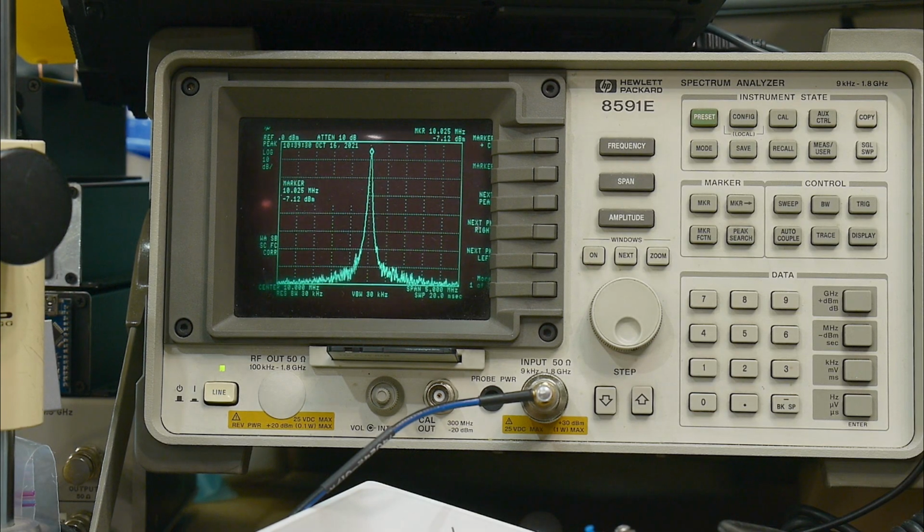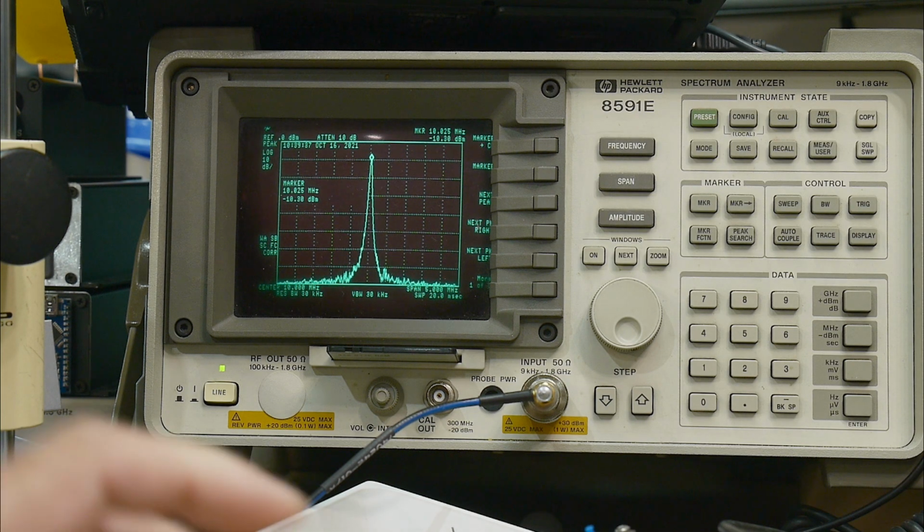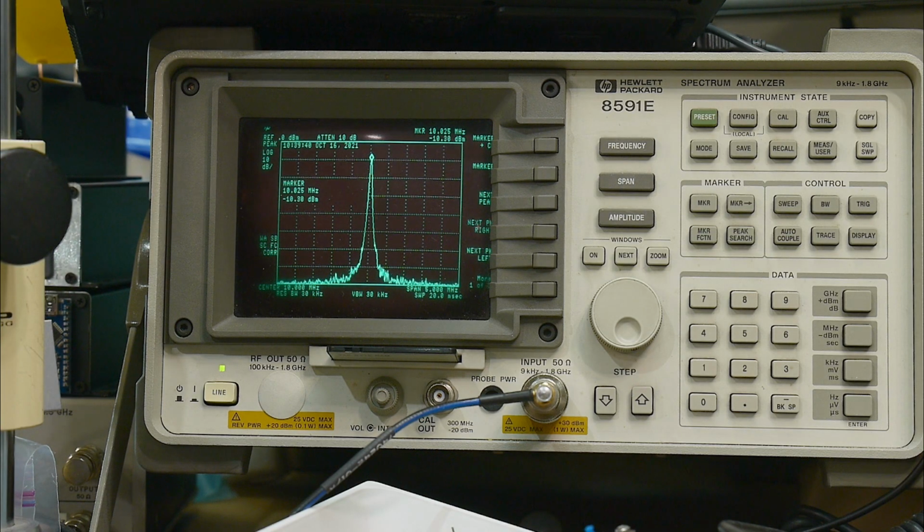Okay, so let's get this out of the way. You can change the level, so let's go to minus 10 dBm, and you can see we've dropped down. We're at minus 10.28, and then you can hit some buttons here too. You can hit the minus 10, it automatically drops by 10. There at 20, 30, 40. Oops. Where are we? Minus 50, 60, 70, very nice, and it stops at minus 76. So it does that perfectly. That's really, really good.